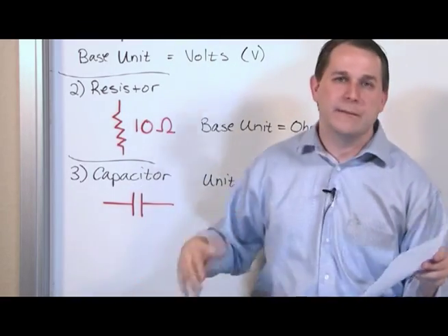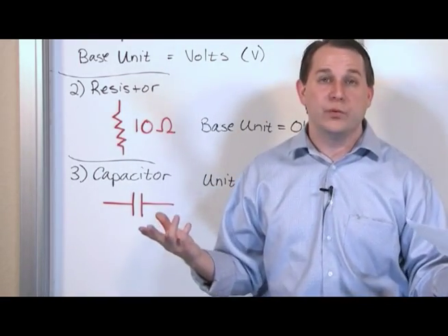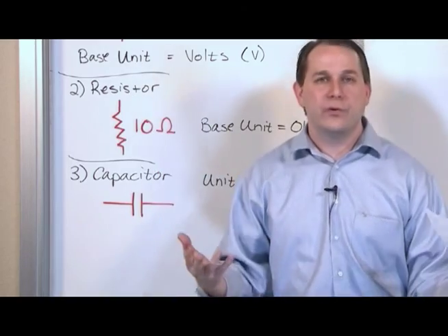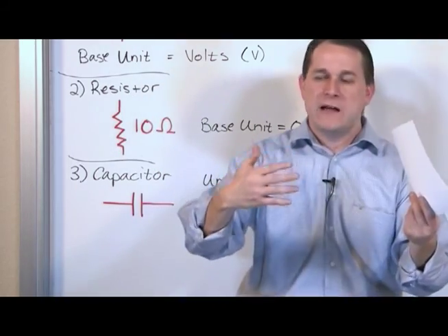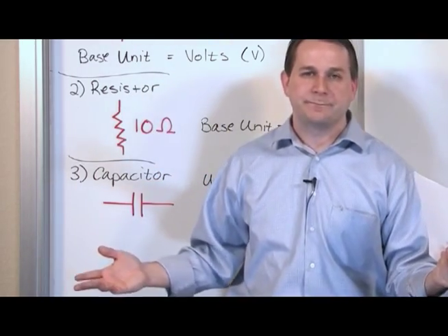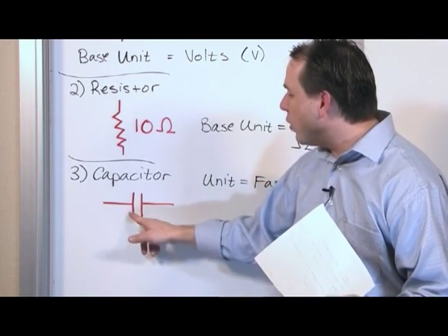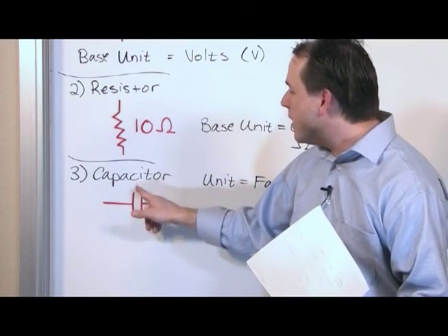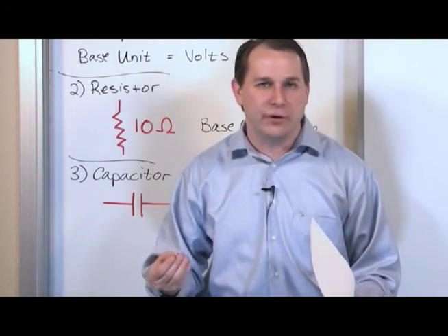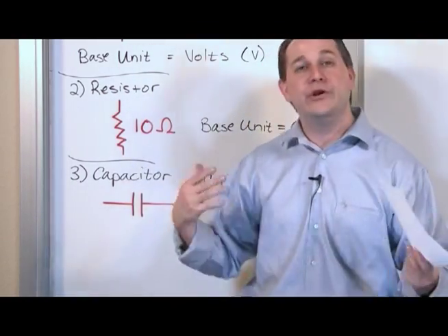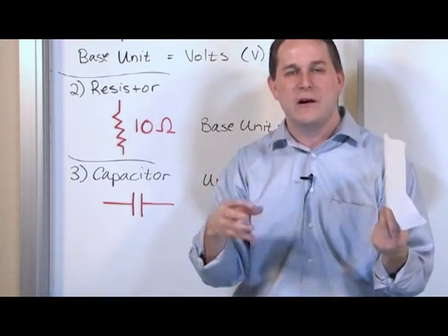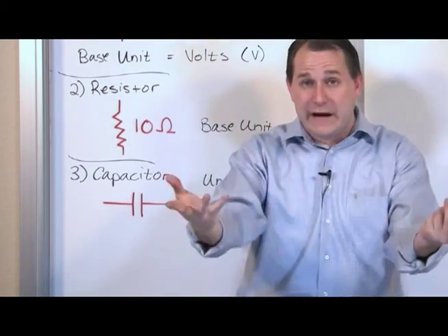This is probably one of the most intuitive ways you could think of when you would want to use a capacitor. So it's a storage device. You put charge in, later on you can take charge out. That's the simplest thing. The energy that's stored in a capacitor is because of the charge on the plates here that are not touching, but also in the electric field that exists in between the plates when you charge it. Because when you put all those charges there, that electric field is going to be there.